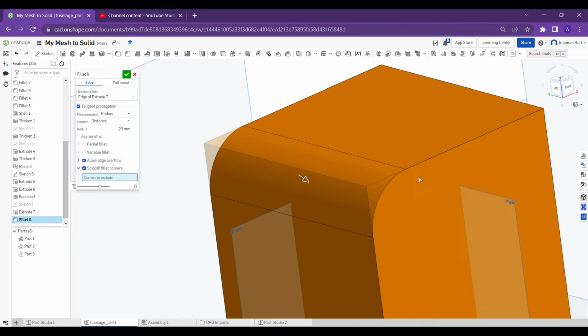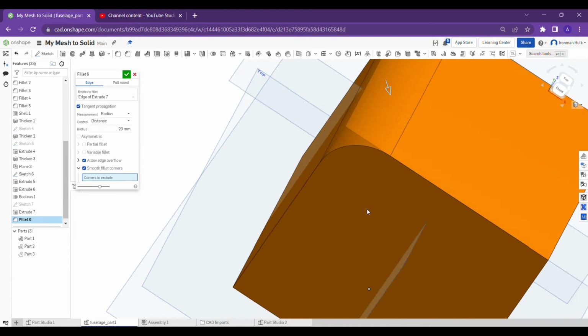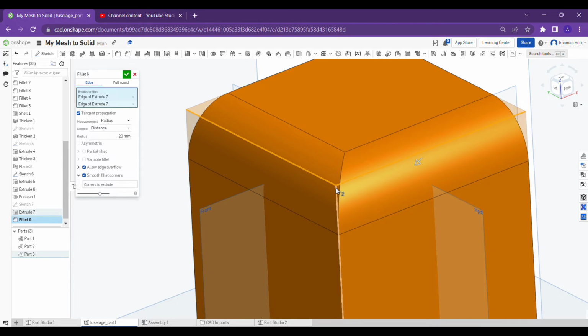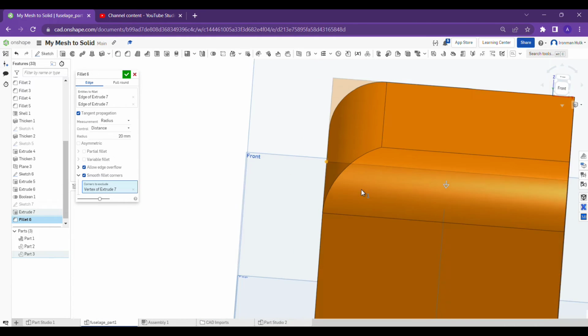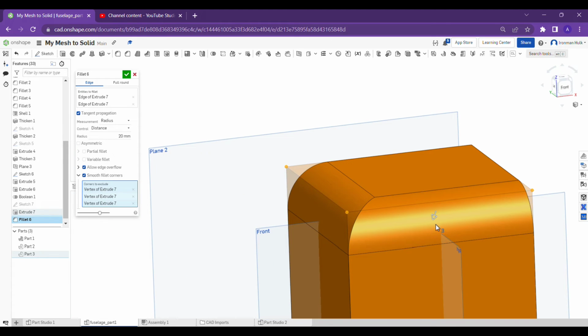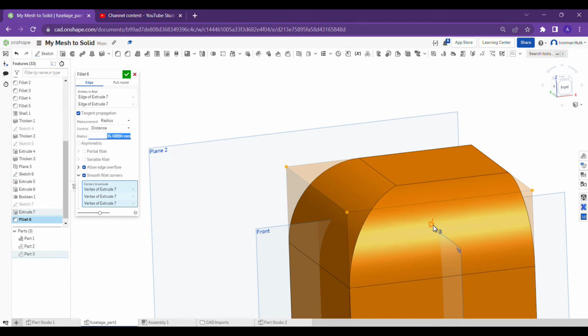You can add as many points as you want, and another one is edge overflow, and another one is corner points, which means wherever you are doing the fillet operation, you may observe the corner points. You want to smooth these corner points using this tool. You can observe it by trying. At the vertex point you can get smooth edges. In this cube it is already smooth, so it will not show another way, because it is already smoothed in this particular cube.